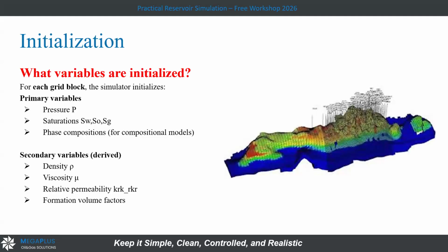You will see the simulator is split into something called black oil simulators and compositional simulators. In the black oil simulator, it depends on lookup tables that are done in the lab. And in compositional, we are dealing with something called an equation of state, to see the phase changing with the composition from C1 to C7 plus, or until C20 maybe.